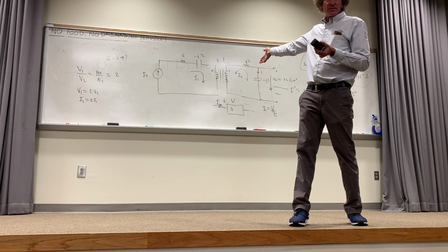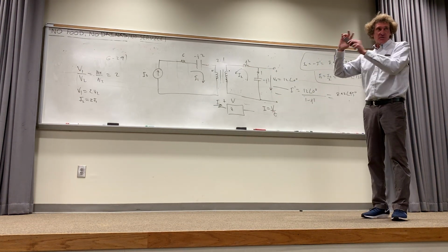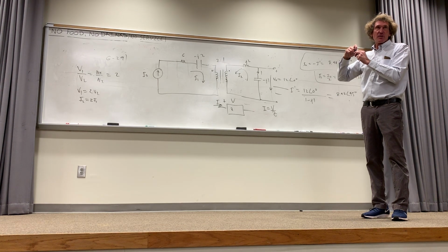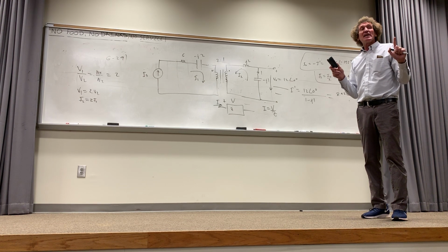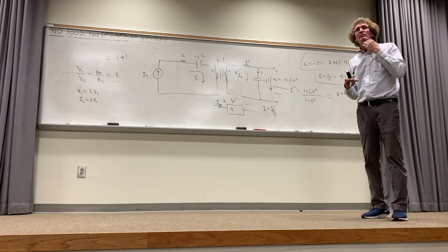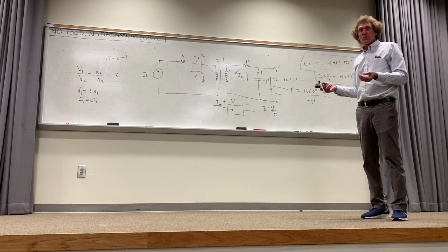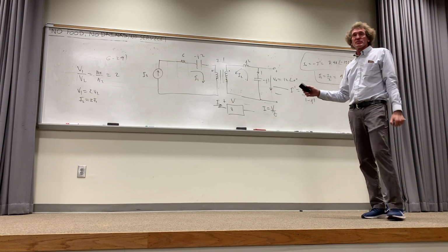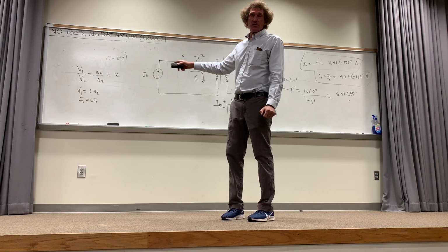You have two distinct things given by these equations. I can show you that with magnetically coupled circuits, the way we drew them, if it's strongly coupled, in other words, if the square root of L1 L2 is equal to M, then these equations hold. But with a magnetically coupled circuit, they don't even mention the turns, right? Is that why it says ideal? This is an ideal transformer, but almost all transformer equations don't use the mutual coupling equation. You don't have j omega L1. You don't even know what L1 is, frankly. You just use these equations.